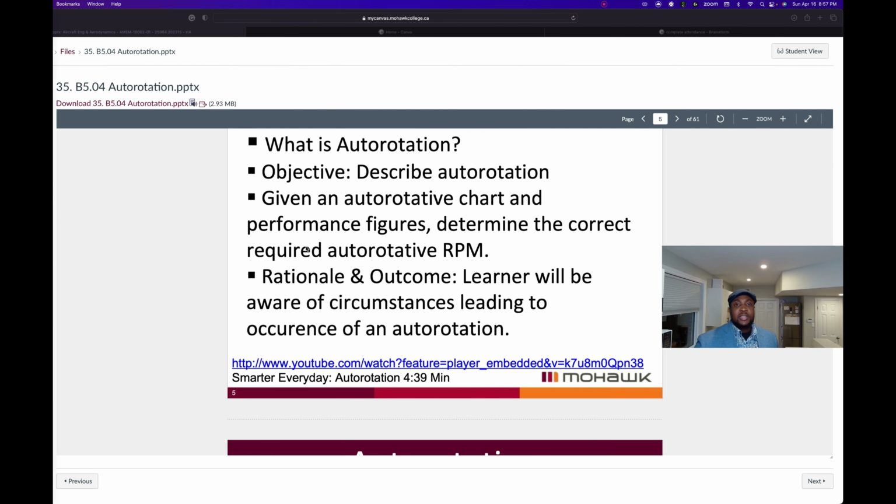The rotor is divided into different sections for explanation when it comes to autorotation. The rotor can be divided into 3 regions when the helicopter is in vertical descent or in autorotation. One of these areas is known as the driven region, and the driven region is the outermost region.